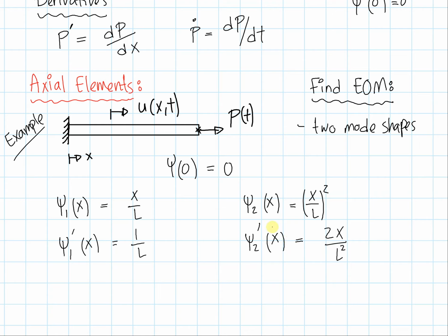All right. Now, how do we go about solving a problem using the method of assumed modes? The answer to that is virtual work. We're going to introduce a couple of relationships that describe the energy in our system, externally applied energy and the internal energies, and we make them equal, because total energy is always equal to 0. Anytime you're dealing with the method of virtual work, you're thinking about the sum of energies that are equal to 0.